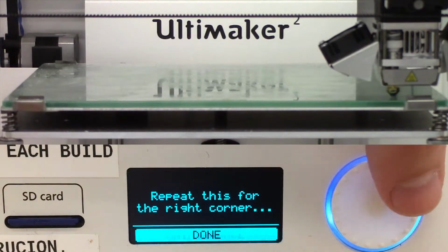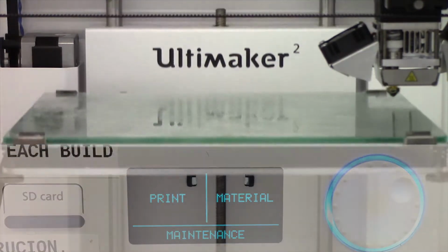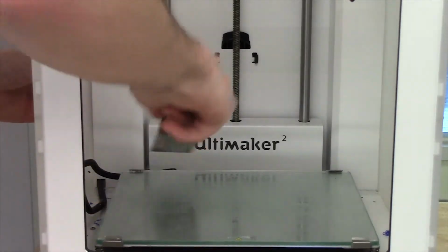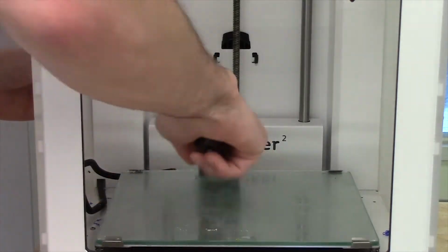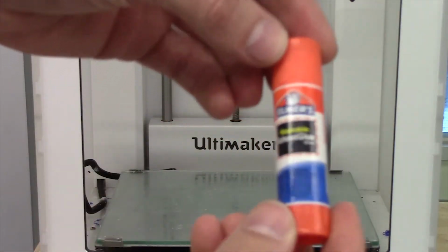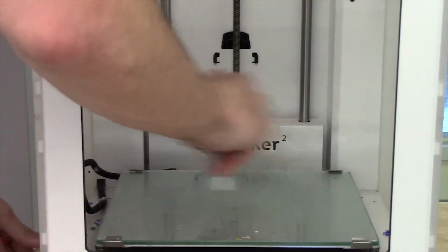A way to minimize this is ensuring that the printer tray is appropriately in line with the plane of the nozzle's guide rails. Next up, we'll take our putty knife and scrape away any remaining adhesive or print material on the glass tray, and take the glue stick and apply a layer over the region of the build tray that will interface with our part.